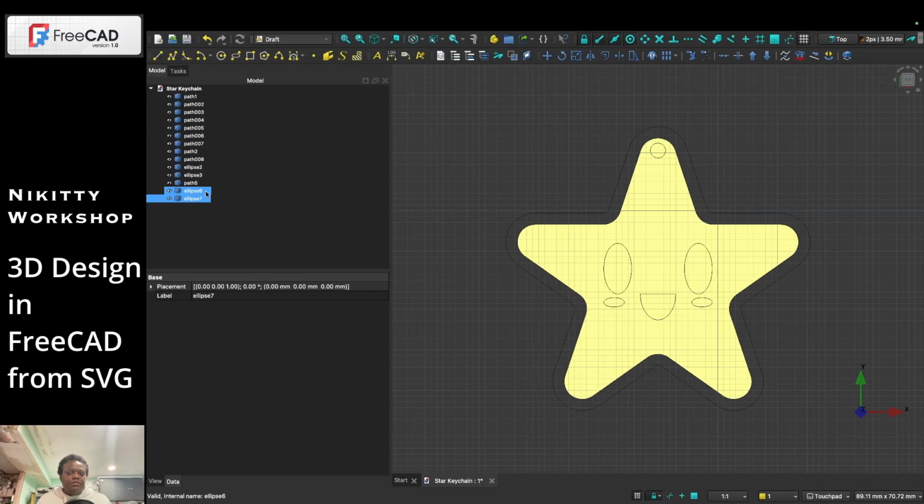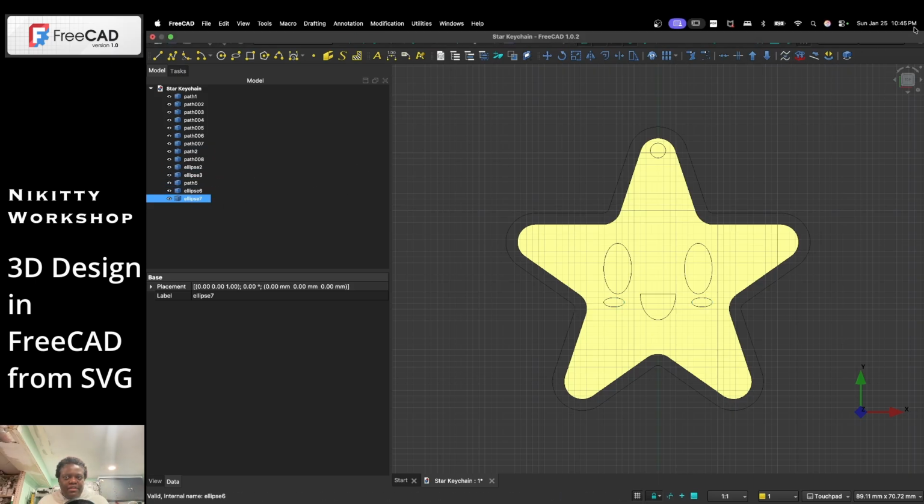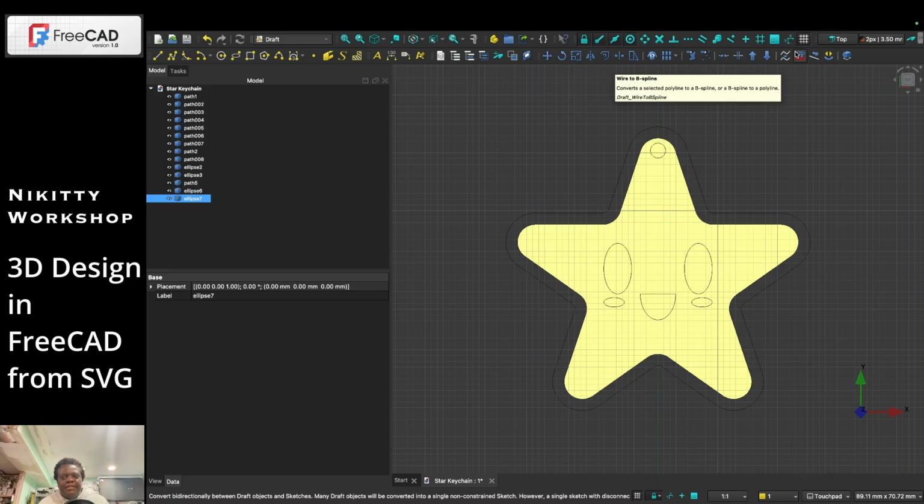All right, so like I said, we want to do the cheeks together, so that's one cheek, two cheek. So we're going to select both. I did Command and click on the two of them. You could have extruded them individually, like not extrude, sorry. You select one and you could create a sketch from it individually.